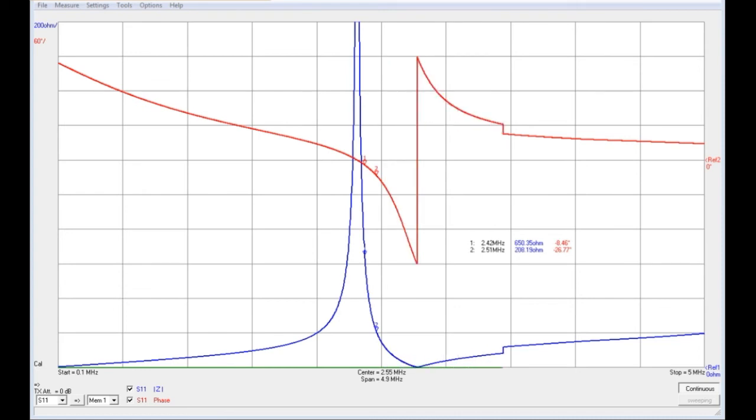The nice arrangement of these cylindrical coils is that the primary can be moved right inside. Now you see that changes significantly. It's pushed the series point up. In other words, those coils interact very, very strongly now. The coupling's quite tight. The beating between them is quite a lot. We see we've separated further that phase transition and the peak and the trough in the magnitude of the impedance.